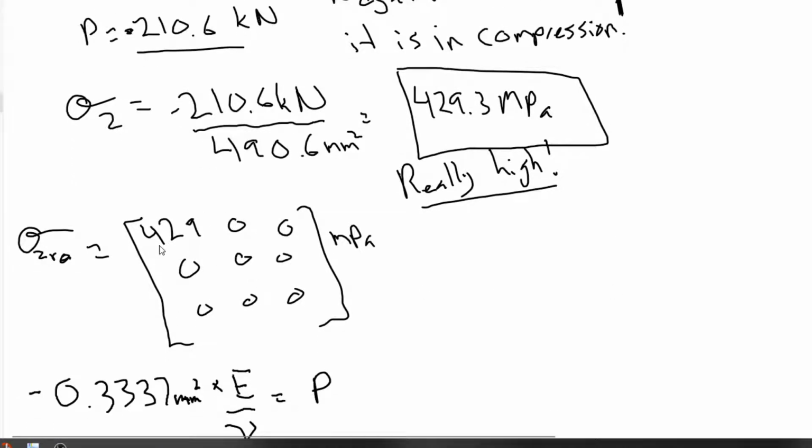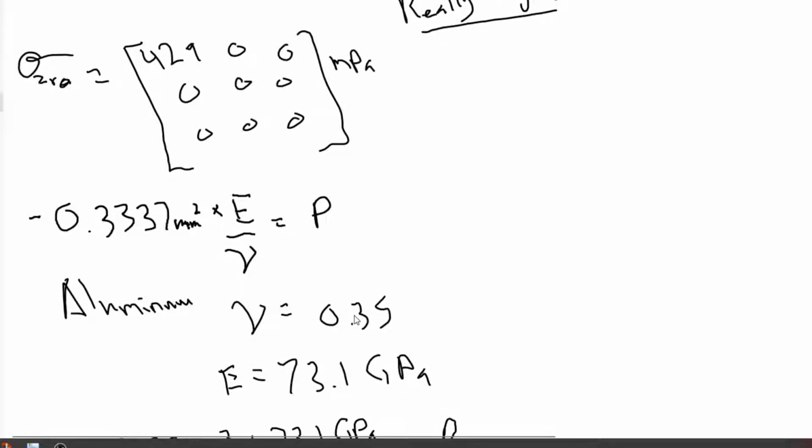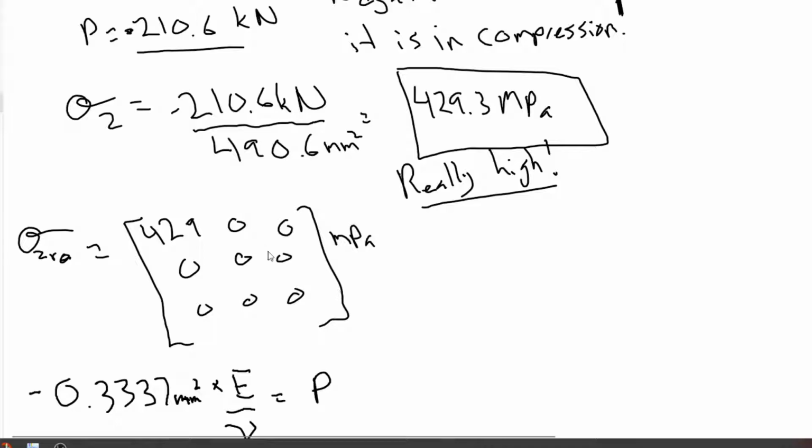So it would have a stress state of this. Our sigma z r theta. When I'm working in polar coordinates, I like to put which order they're in underneath the sigma here, because when you're working with x, y, z, everyone knows that it's x, y, z, whereas with polar coordinates, people aren't quite as used to doing that. So I like to state it directly, which is which. Some people choose different ones that kind of go in which position as well.